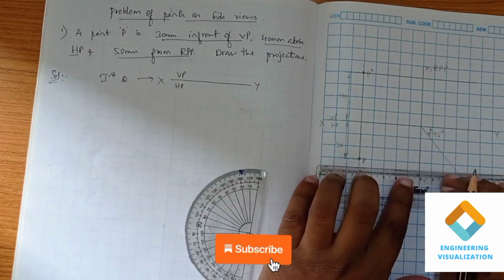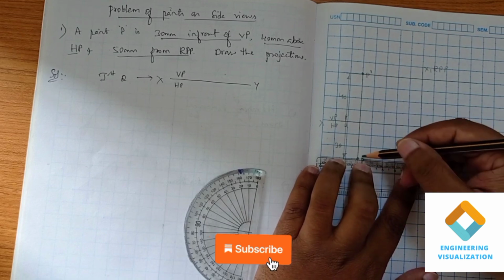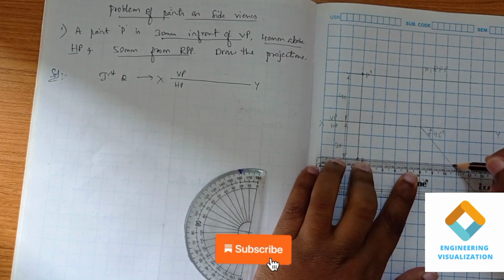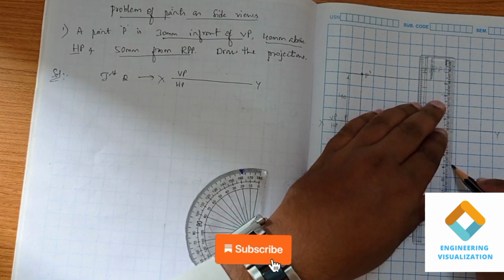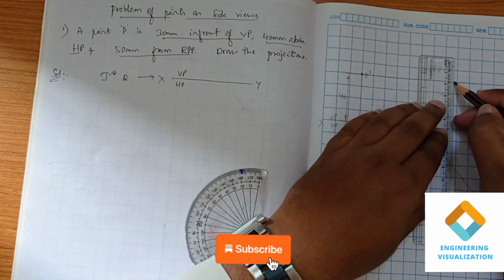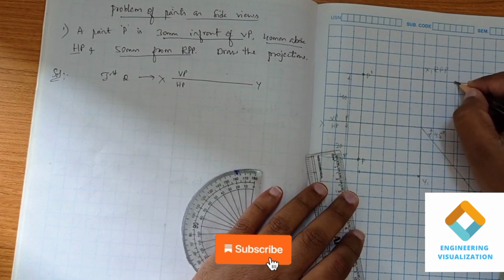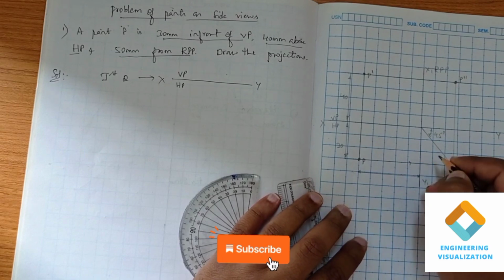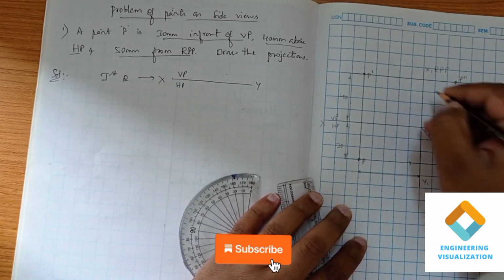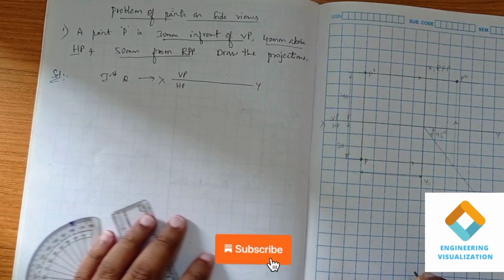Now from this top view, draw a straight line until it touches the 45-degree line. Then we project upward. Where these two lines intersect, this point is our side view. And we can show the direction of the projection line. So this is the side view.